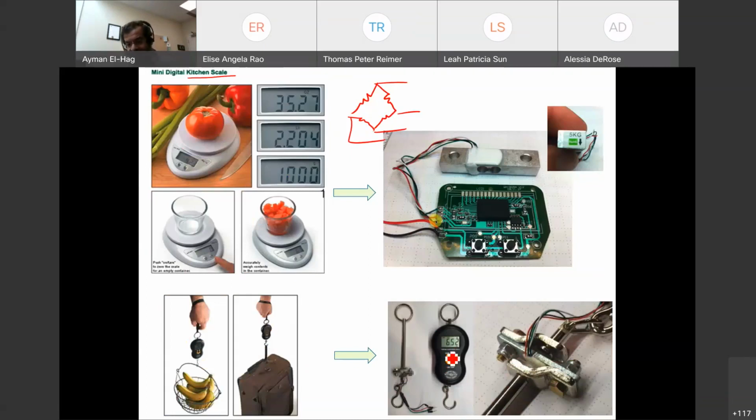So here, as I said, if you just open this, you see here a digital screen, call it LED, or LCD. You will have something like this in your kit, and it can easily be programmed to show the readings as numbers. But again, there should be some code to do a conversion between the voltage that you are measuring and the actual force that is applied. Okay, very good. So this is the load cell.